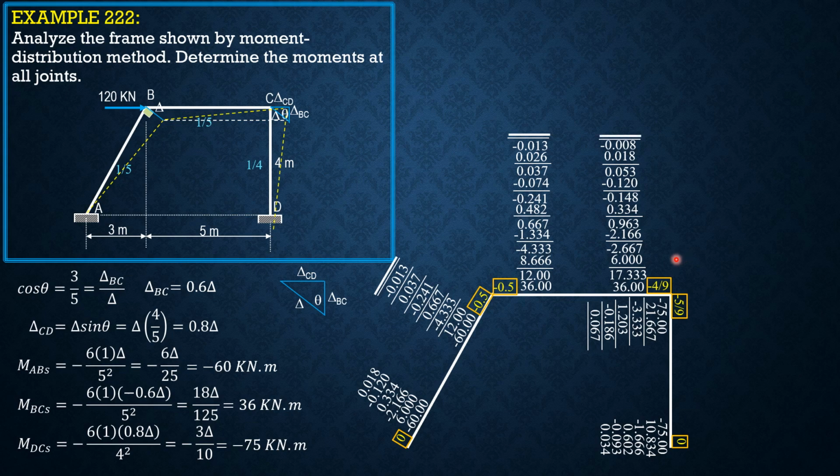So let's have our static equation in order to solve for the constant ratio R. So we sum up moments about O. Let's find O. Let's call that theta. Let's call this Y and Z. And remember the slope 3, 4, 5. So Y over 4 equals this distance 5 over 3 equals Z over 5. Then these are the support reactions at A, support reactions at D.